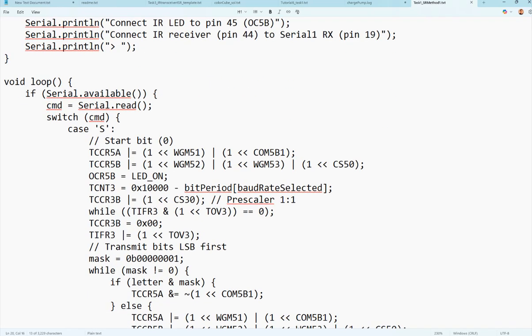So it gets into the loop. It's detecting the command that you are sending to it. So first you want to send it, right? When you are sending it, the first bit is definitely a 0 bit. It's the starting bit, right? So if you want to send a 0 bit, you want to turn on the PWM, because whenever it's on, the decoder will receive a 0. So it's pulling it down to start the UART communication.